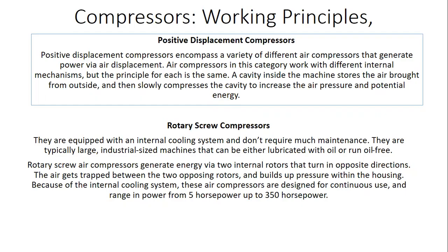I'm sure as I'm explaining this, your mind is running free. You are interchanging what you are reading and what I'm saying with your mind. You are imagining this happening. Two rotors are enclosed in a housing and they are rotating in opposite directions. When air is sucked in, the air is trapped in that housing in between the opposing rotors. Now, this builds up pressure, obviously, within the housing.